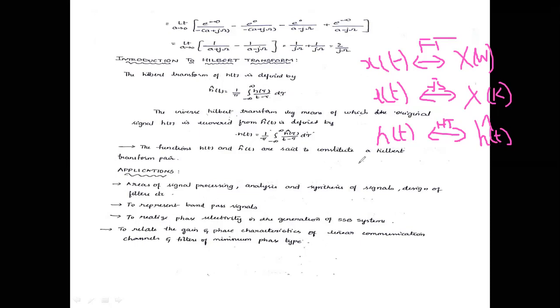And 90 degrees phase shift is there. The Hilbert transform introduces a 90 degrees phase shift. Carrying it out twice causes a 180 degrees phase shift, which can cause a sign reversal of the original signal. If it is 90 degrees and again 90 degrees, then the sign of the original signal is different. Plus becomes minus and minus becomes plus, my dear students.